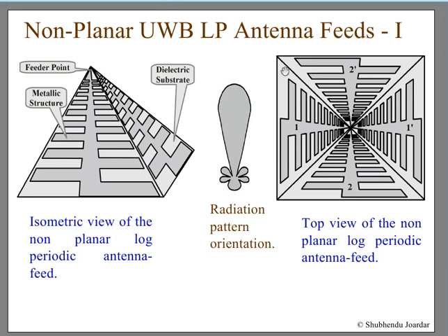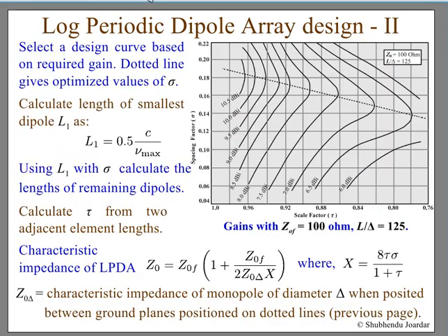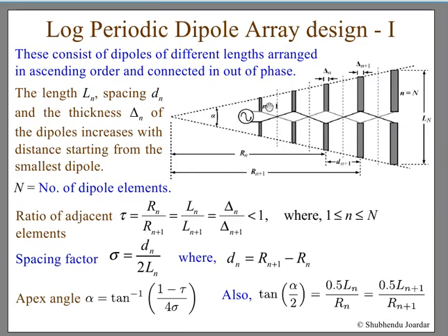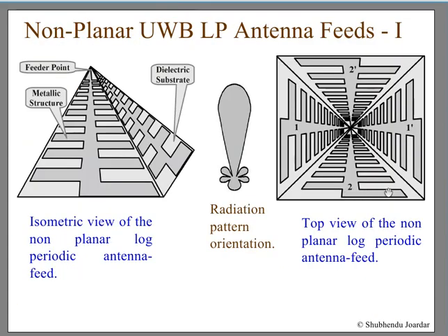So you see that in the transmission line you have to put it crisscross. So you have to connect it oppositely. The next dipole should be connected in the opposite way. So you see that one dipole is here, half dipole is here, whereas the other half dipole is in this direction. Then half dipole is in this direction and another half dipole is in this direction. And between these two points at the center, you are connecting the source. That's for one polarization, and similarly you have to do it for the other polarization. So one will be for horizontal, this is a horizontal polarization, and this is for vertical polarization.